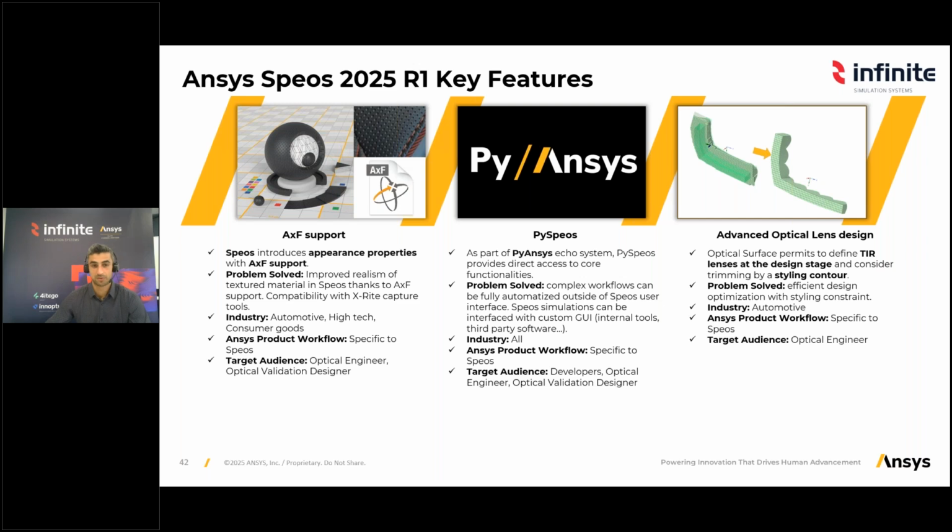Similar to other products, there is some advancement in Python scripting with Ansys, and in this case more specifically Speos, to build workflows and customize simulations. There is a great GitHub page, by the way, where you can go and look at scripts that are shared by other companies using it, or find some models or some guidelines on how to use that. And then a third one worth mentioning is the optical lens design, which was improved with the possibility to define TIR lenses, so total internal reflection lenses. Also a nice improvement in Speos.